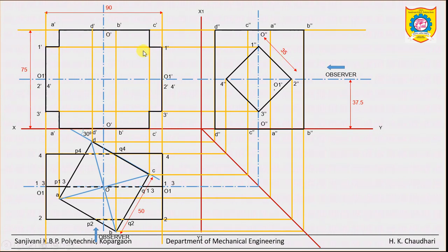Before that, just see in the front view, this is the outline. Outline means the outside portion of the intersection. Clear? This plus-like structure, we have to now make the internal portion. Okay, so first of all, draw the vertical projection from point number P1.